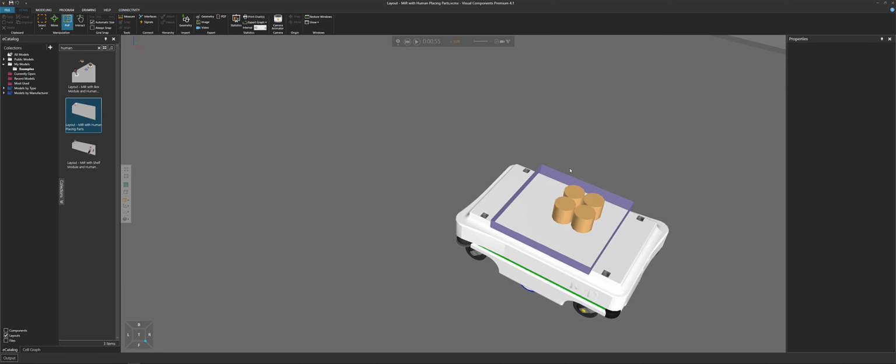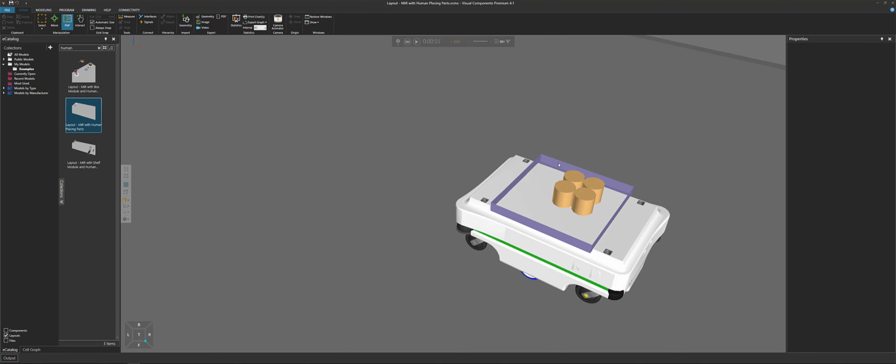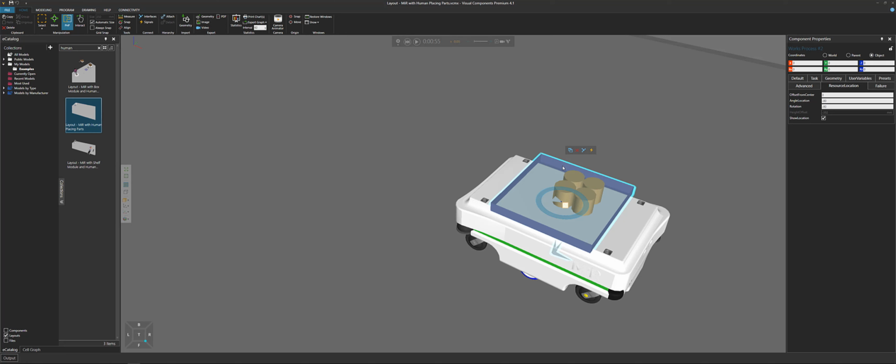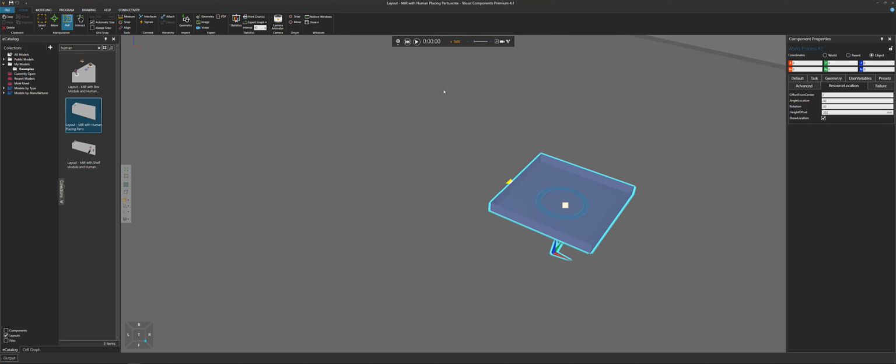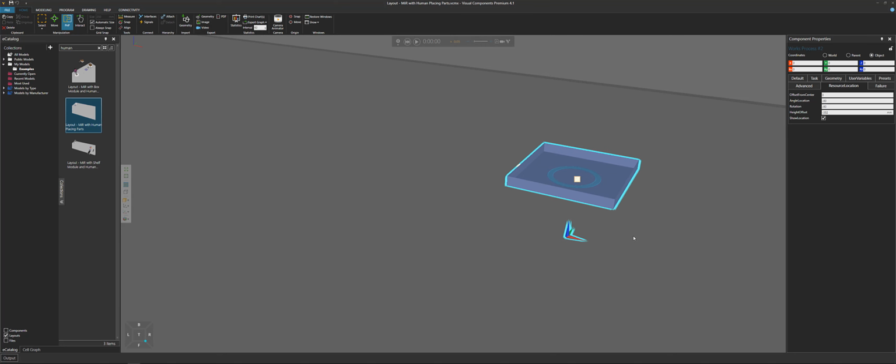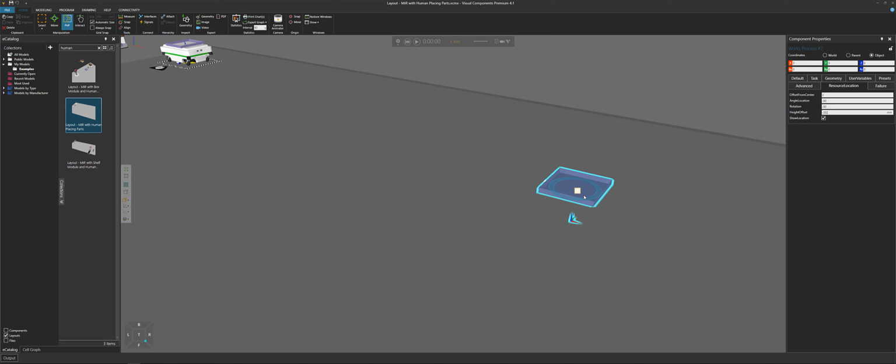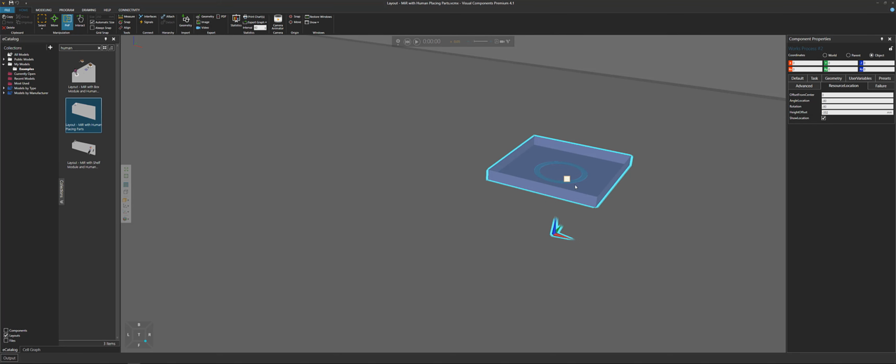And one thing to notice is that our vehicle is driving to and from the stations, and I position the stations in a way that the vehicle can go underneath them. So if we reset, the tip and trick to make your vehicle go underneath the work process component, not to see it as an obstacle and avoid it, is to adjust the height